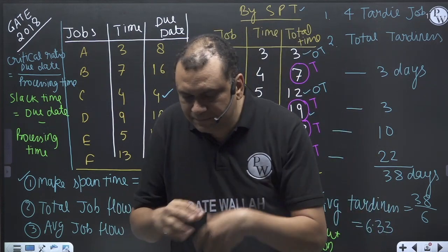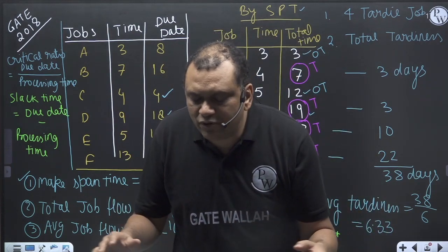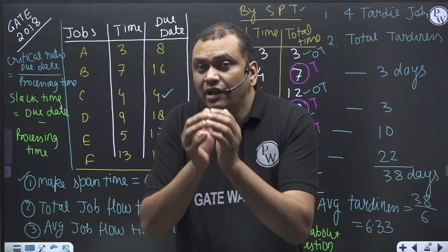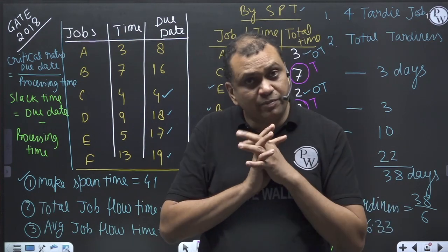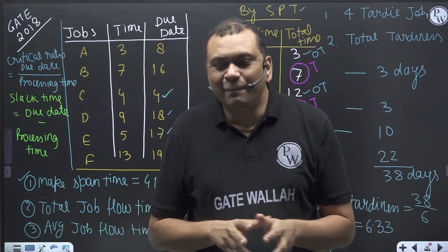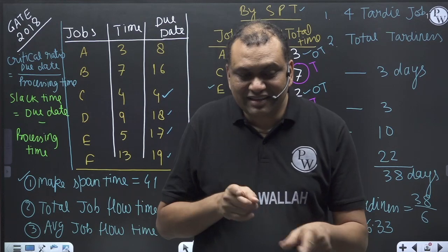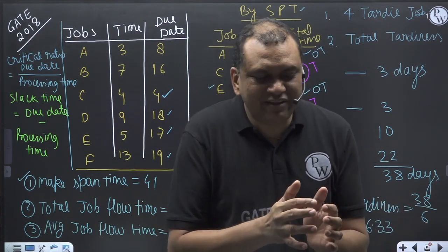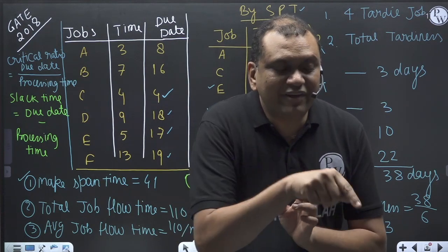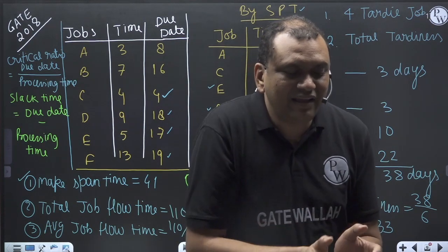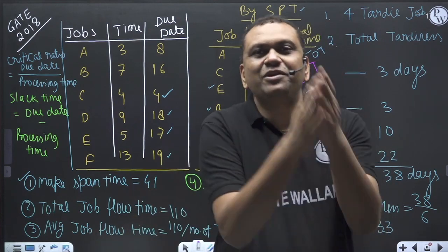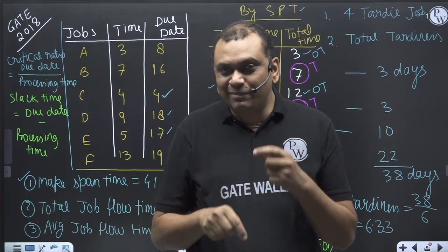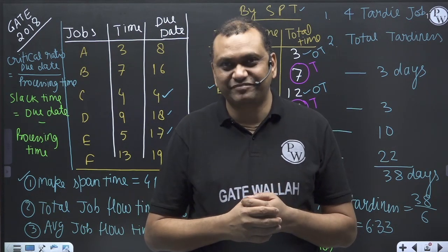After machining, the robot is supposed to pick up the semi-finished product and place it in the output bin. But the robot finds that the output bin is full. So the robot is waiting with the job for space to be created so it can dump the job into the output bin. This is called blocking of the robot.